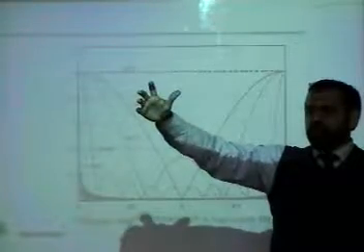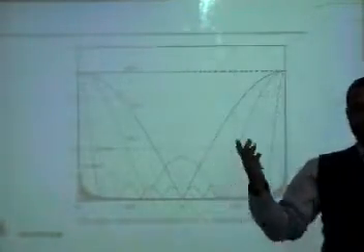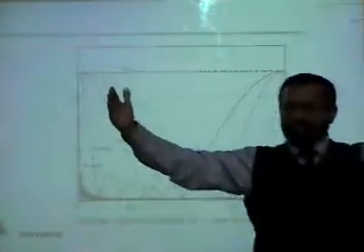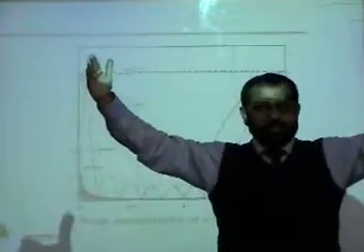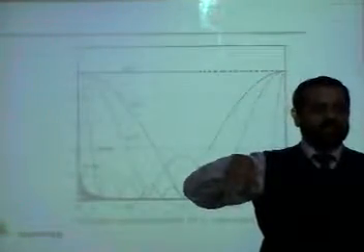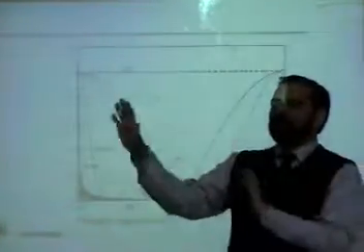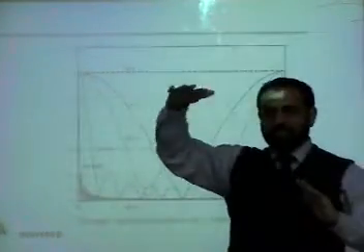What do I expect to get at the output? Almost a DC value, because I'll be getting the same value. Why? Because I'm taking 1000 samples average, then I'm moving and again taking 1000 samples average, where 999 samples are the same. Obviously I'm going to see the same thing. So it means I will remove all the frequency content. There will be just kind of a DC value.